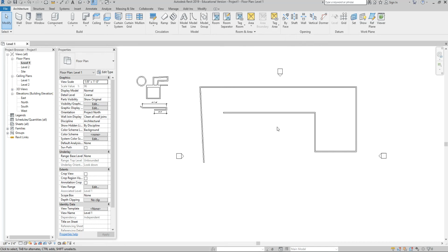So it's something that you can place on your drawing board that will allow you to visualize something, but it's not an actual object. It's just a reference, okay? It's a reference plane. So these reference planes, they're green, they're a dashed line weight, they don't print. They're just there to help you draw geometry, essentially, okay?